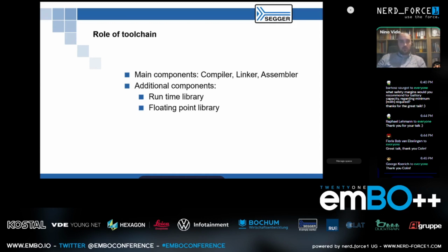Of course, if you have a hardware floating point unit, your hardware takes care of this, so the code is already very small. But if you're running on a target device that does not have a hardware floating point unit, it's usually nice to have a great floating point library that has very fast and small code for your floating point operations. So the difference between a hardware and software implementation gets smaller, and you can still use your floating points.